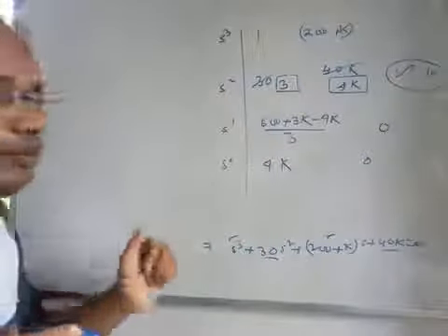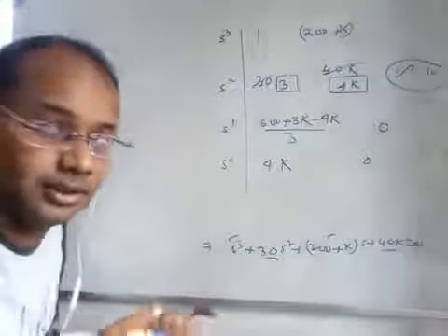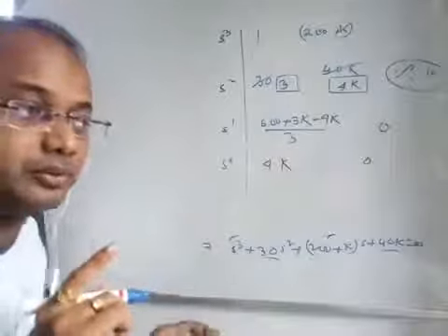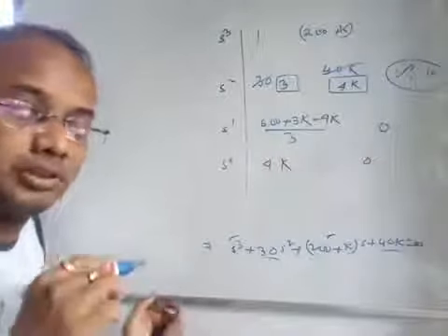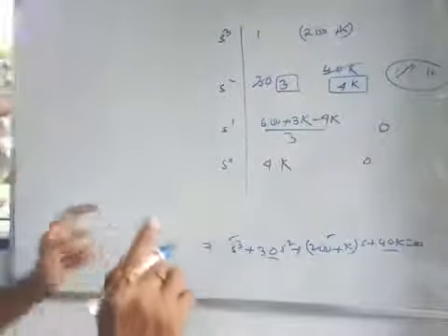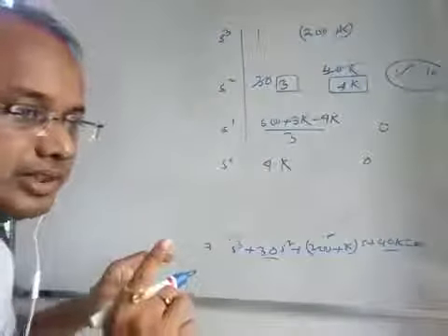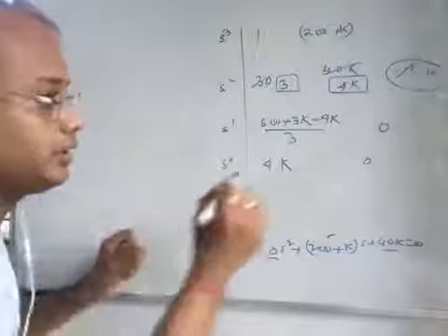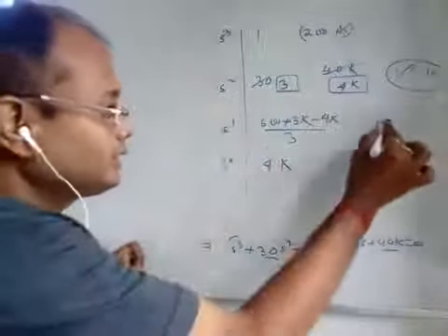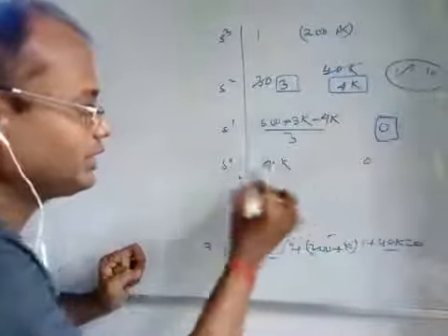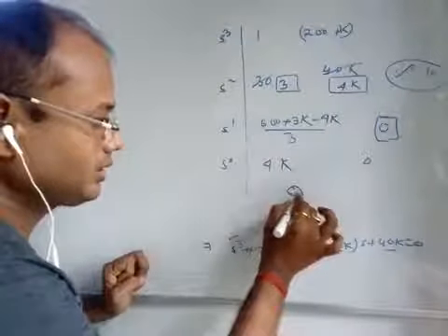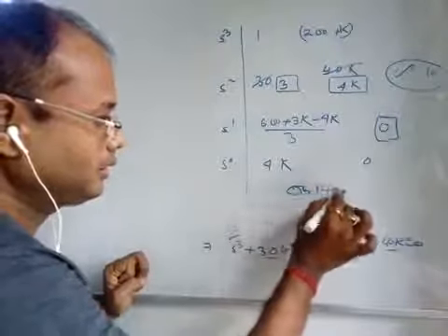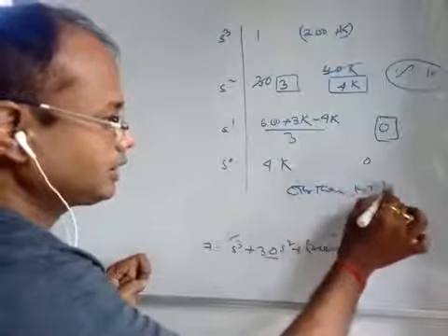Now the question is that you have to find out the value of K for which the system will be marginally stable. If the system has to be marginally stable, then all the elements of a particular row have to be made 0, other than the last row.